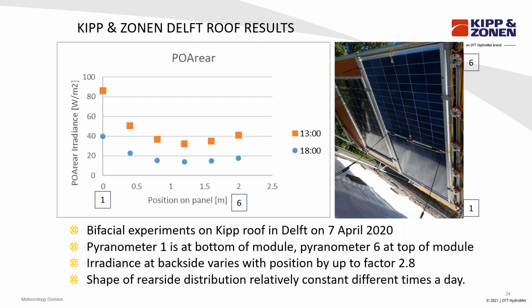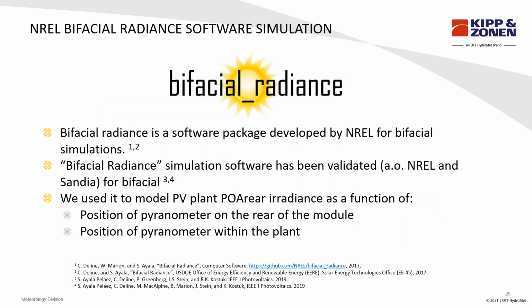Now, to make a broader assessment of mounting recommendations, we have employed a software tool called Bifacial Radiance, developed by NREL, and the links are below here if you're interested in it. This software has been extensively validated by, amongst others, NREL and Sandia labs, and we have used it here as a model to come up with recommendations of the position of pyranometers on the rear of the module and the position of the pyranometer within the plant.